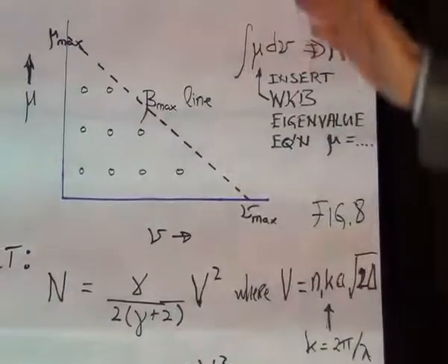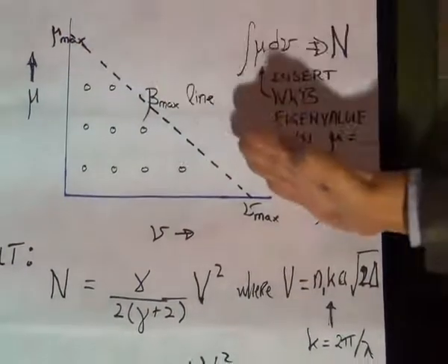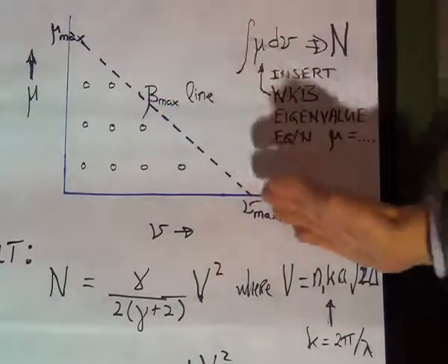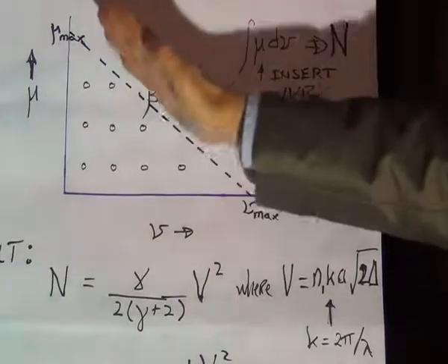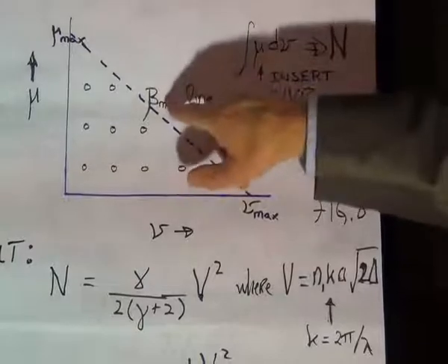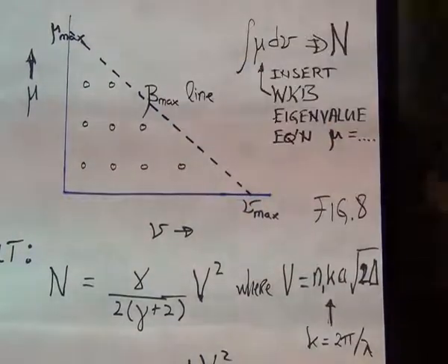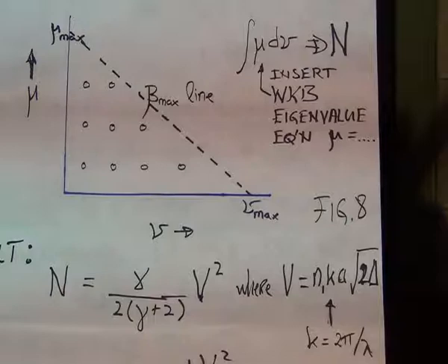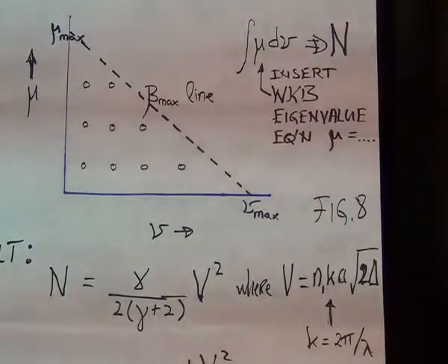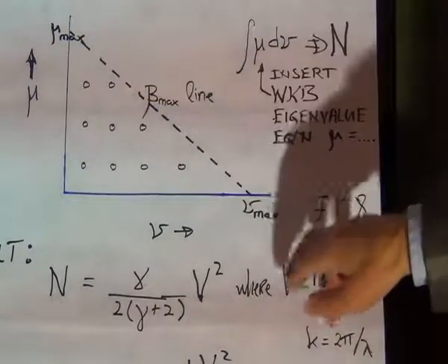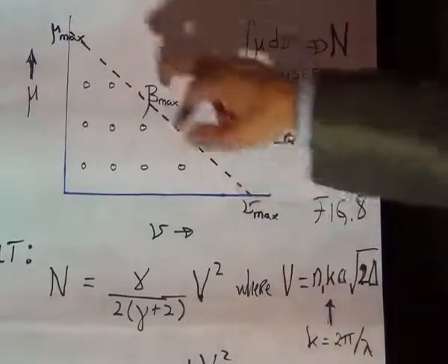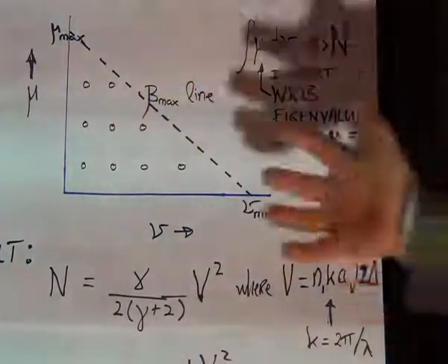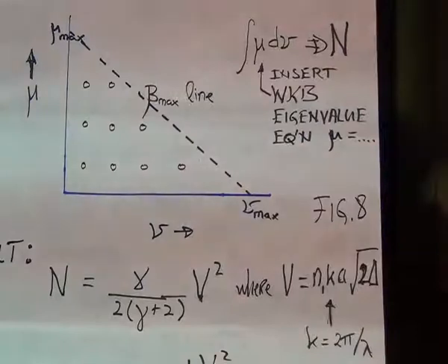And it turns out there's a line along here, shown here, which corresponds to beta, and you could keep moving beta out until you get to the maximum permitted beta. We just calculated that; it's N1K. You can stop the line at that stage, and now you find you have a maximum nu and a maximum mu. Now if we count the dots, we've got the number of modes, we think.